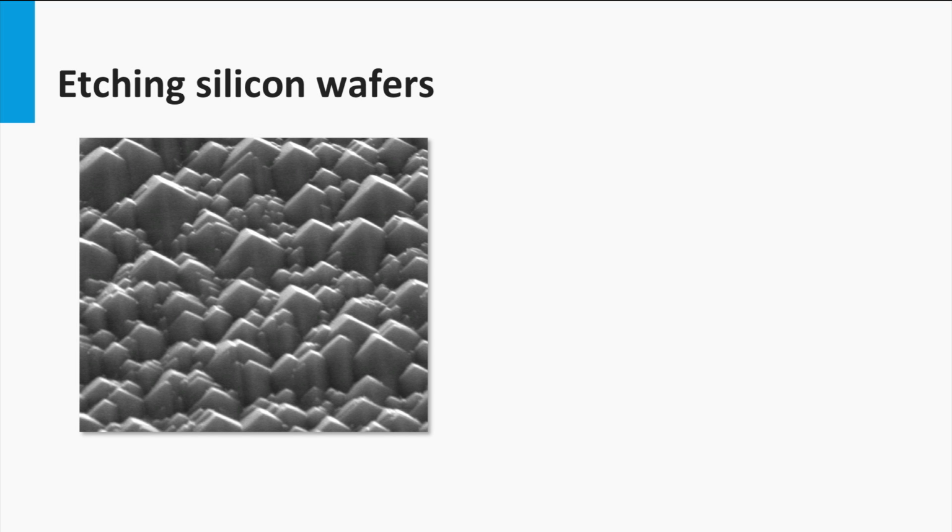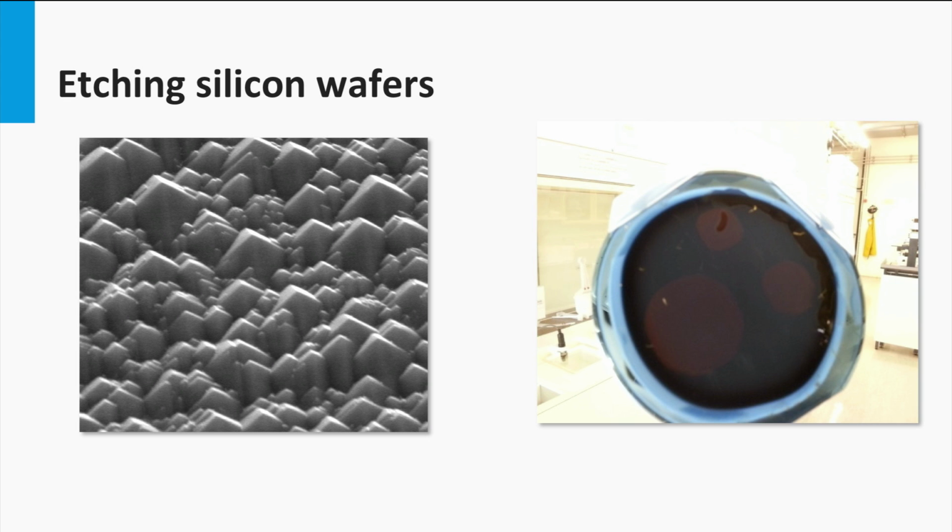The texture on the wafers can be realized with wet etching approaches. Here you can use an interesting property of the 100 surface. This anisotropic etching can be used when etching a crystalline silicon wafer with an initial 100 surface orientation. Etching of such a wafer leads to textured surfaces with a pyramid structure having only 111 oriented surfaces. In this picture you can see such a textured surface of a monocrystalline silicon wafer as processed at the DEMUS lab in Delft. Using such etching procedures, it's even possible to have a silicon wafer looking black as shown here in the second picture.